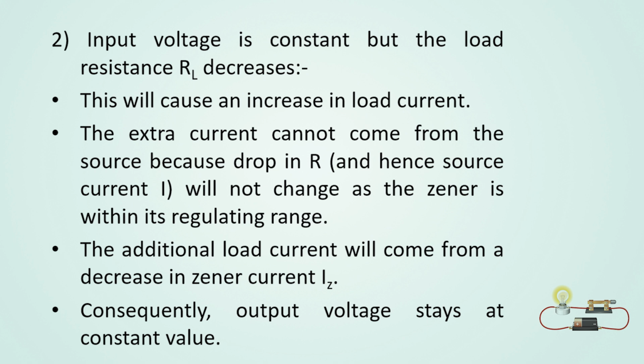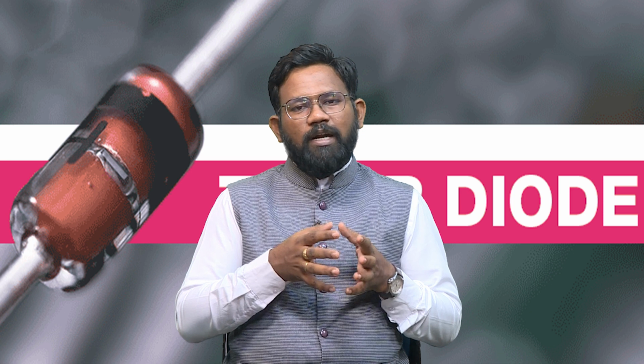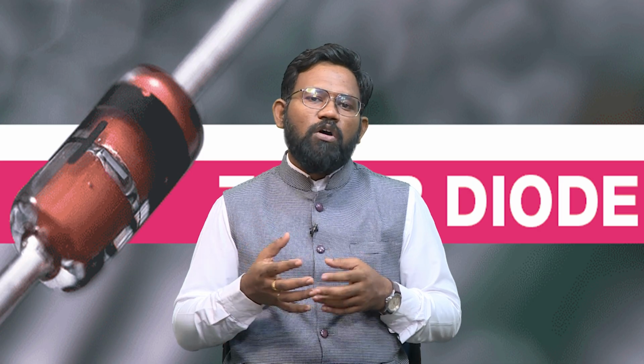So, the additional load current will come from a decrease in Zener current Iz. Consequently, the output voltage stays at a constant value. So, this is how for both conditions the Zener diode maintains the voltage at Vz, so that the constant voltage at the output E naught is obtained.